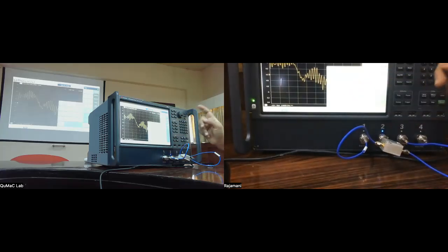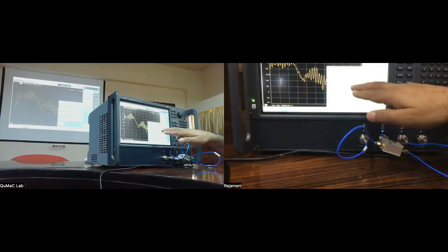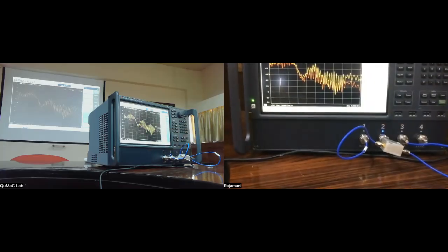So source, S32. Because the source is still 2, and see, it's slightly different, but mostly it's the same. So it's doing roughly equal power over here. So in terms of the regular operation, these are the only 5 important numbers, right? Reflection from all ports telling you that it's matched, and then transmission to the 2 output ports.